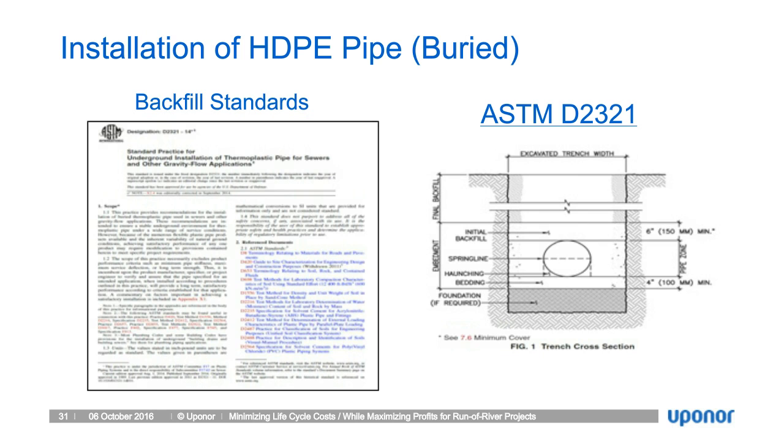The materials being backfilled over top of the pipe and being used as the bedding are also very specific. We look for materials that are class 1 or class 2 at 90% compaction, which should give us a soil modulus of about 2,000 psi. And again, that's the science that we adhere to for the installation of the Weholite pipe.